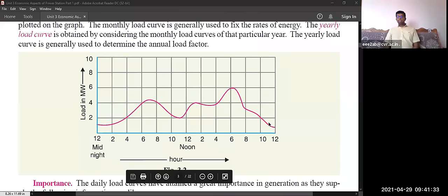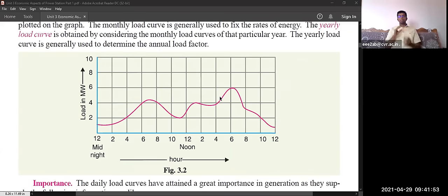So in the generating station also, they will generate based on the previous year's load, approximately, for the same day. So how the load might be there, based on that, they may generate. They may not generate exactly in this range. Combining all the substations, they may not go for exact generation. They may go for some 100 megawatt, 200, 500 megawatt extra only. Why?